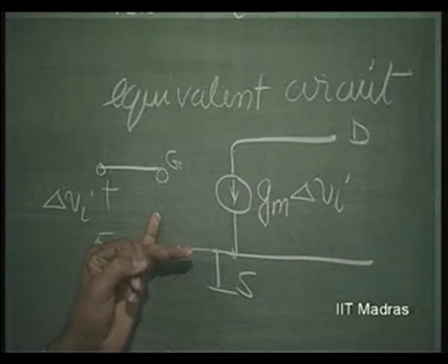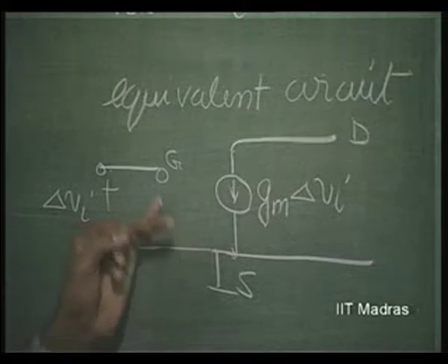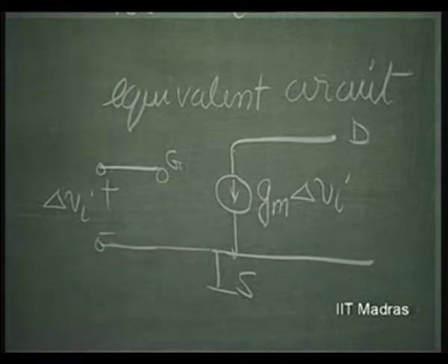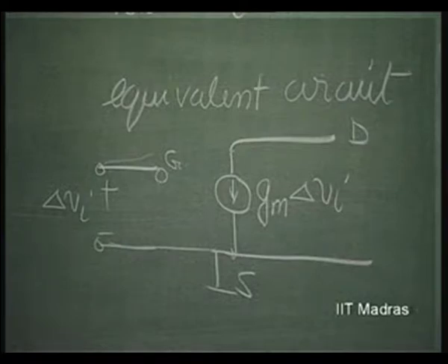As far as the equivalent circuit, the only thing is that at this point it was very nearly a short circuit, because it was current controlled, a forward biased junction, whereas here it is an open circuit. Now, there is a difference between base and emitter. Even though it was a forward biased junction, we had negligible base current if alpha were exactly equal to 1.